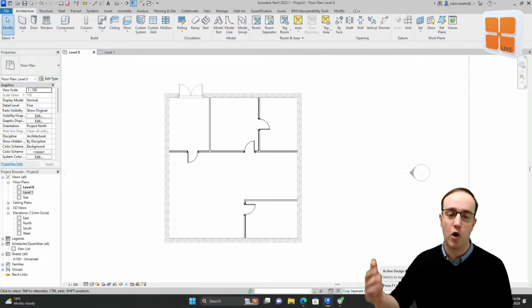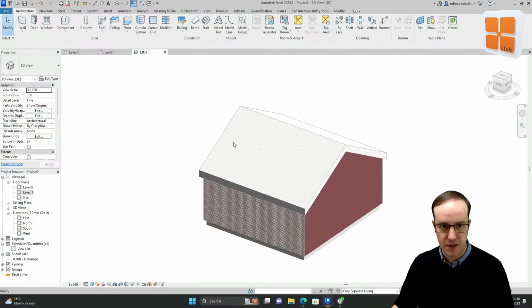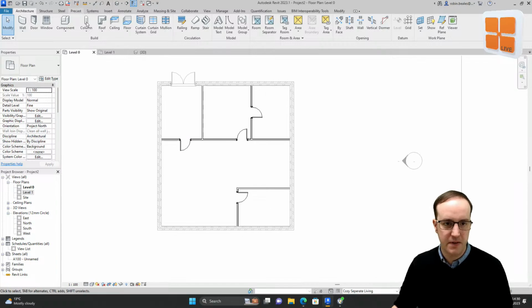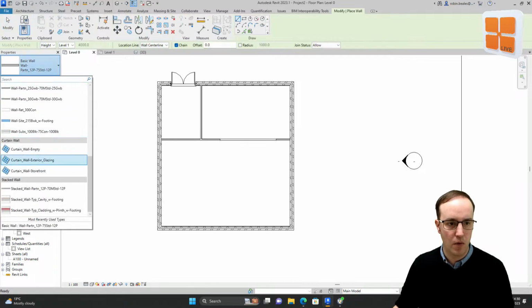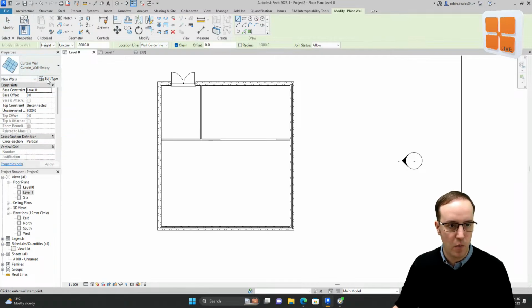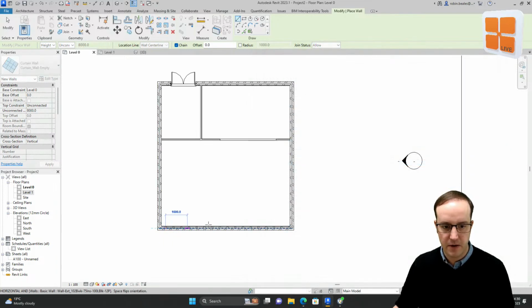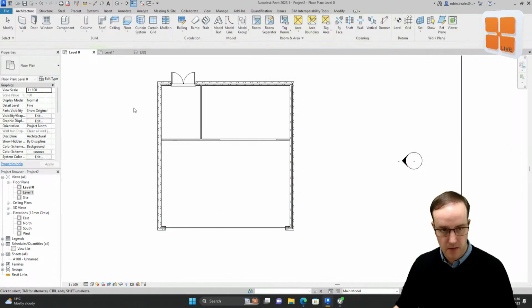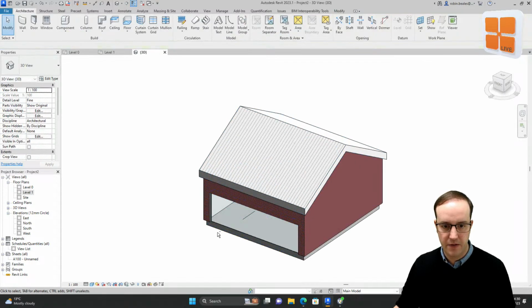And we can have as many different options as we want. And essentially what Revit is doing is it's turning those options on and off. So for the purpose of this, let's just go back to my main model. And against my main model, let's put in a nice big empty curtain wall. Let's embed it just so that we can see from the outside in without having to section the model. Go into 3D, let's just pull that down a little bit underneath the ceiling.